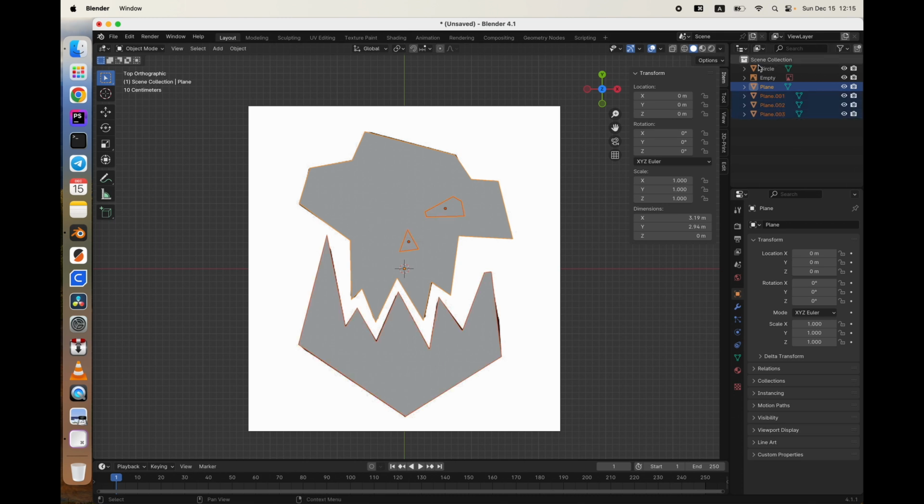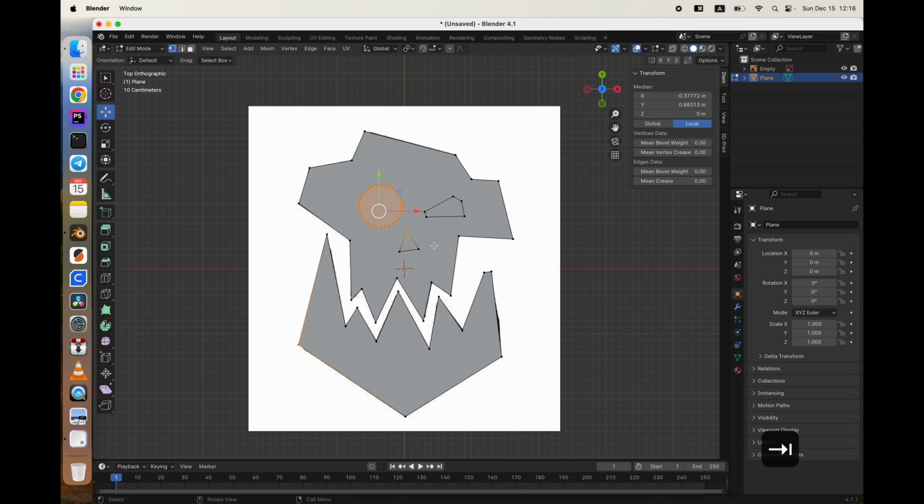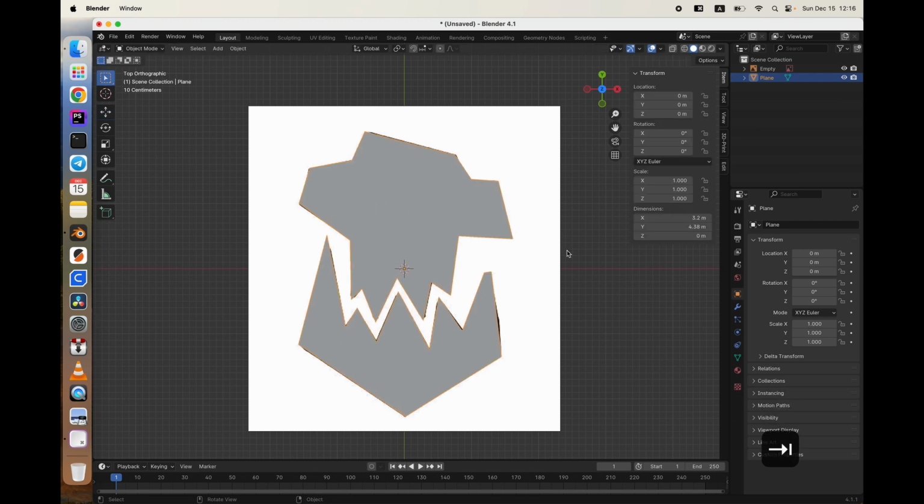Let's select all of this here. Make sure that the skull is the last object selected. It should be yellow. Click it again. You can see that all objects are orange outlined, and this one yellow. It means that it's the active object in the selection, and all others would be joined to this. Press Ctrl or Command G. You cannot see our nose and eyes. It's okay. Press Tab. Everything is in place. Okay. Unselect all. Exit edit mode.